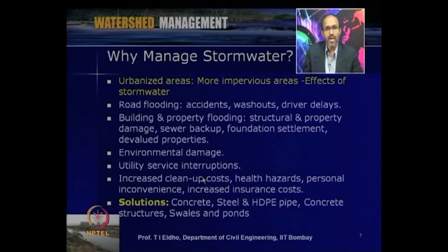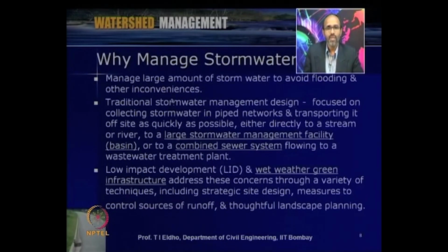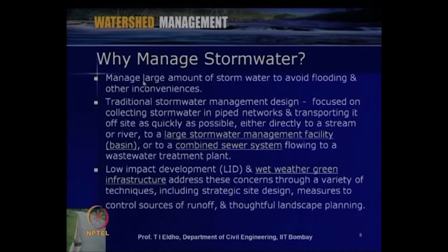Some of the solutions can be, as we discussed, soft solutions like ponds, swales, or wetlands, or hard solutions like concrete, steel and HDPE pipes, and concrete structures, etc. Here the stormwater will be appropriately collected and stored, then treated and released appropriately. That is why we have to go for stormwater management. Also, depending upon the rainfall condition, we have to manage a large amount of stormwater to avoid flooding and other inconveniences.